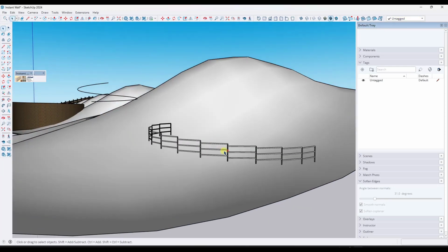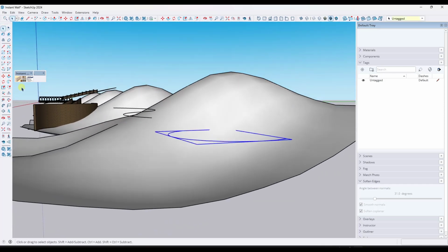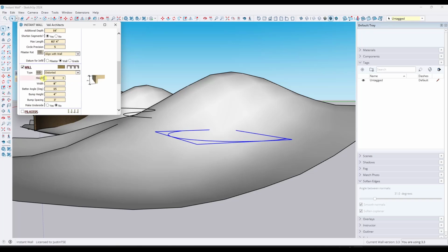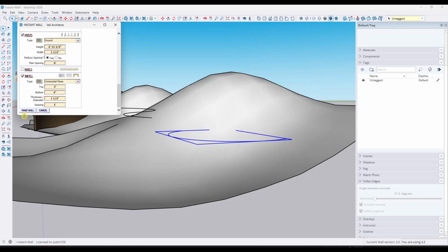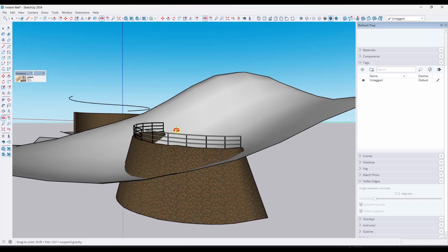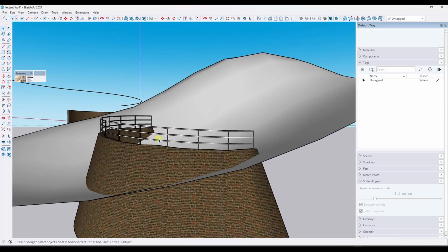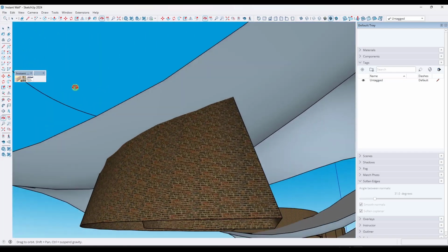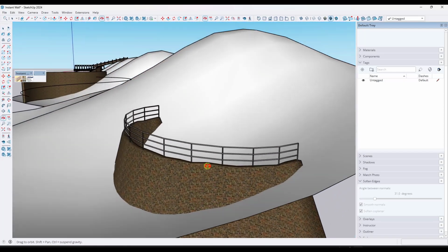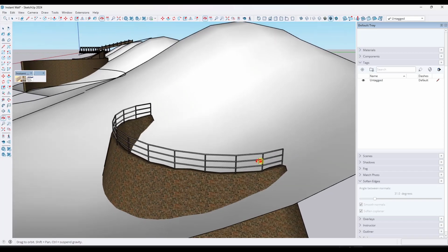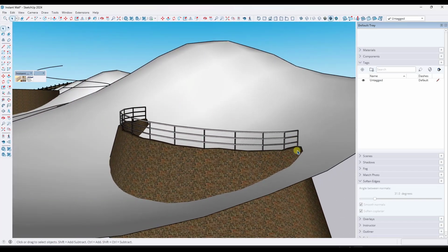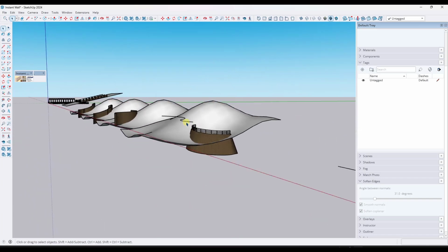So that's actually just going to drop your rail down, which is not what you want, but we can set it to a height of like 1 foot right here, and then we can make the wall. And so what that's going to do is give you this kind of short wall, but notice how it follows along with the surface right here. And it doesn't really matter what you see below ground for the most part, but you can use this in order to create a wall that slopes along a terrain like this with a rail.